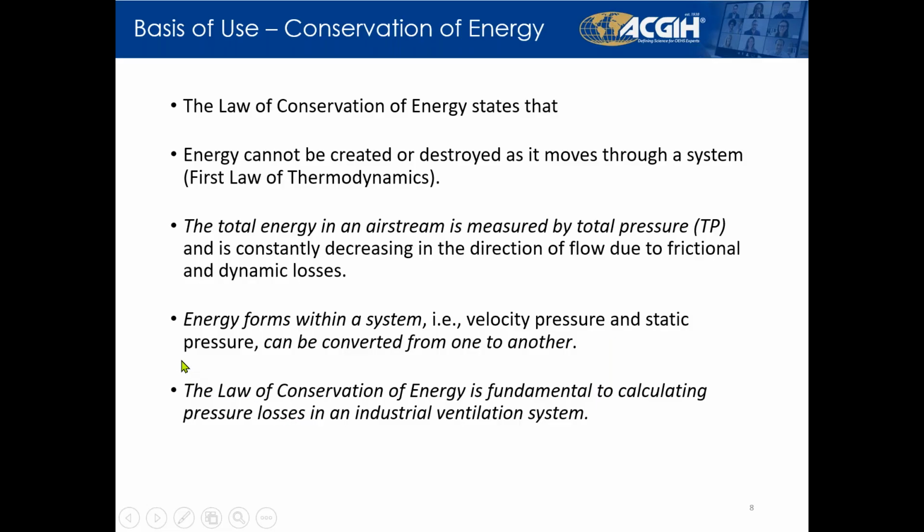Conservation of energy. The law of conservation of energy states, first, energy cannot be created or destroyed as it moves through a system. That's the first law of thermodynamics. Second, the total energy in an airstream is measured by its total pressure, and it's constantly decreasing in the direction of flow due to frictional and dynamic losses. Energy forms within a system, such as velocity and static pressure, can be converted from one to another. And the law of conservation of energy is fundamental to calculating pressure losses in an industrial ventilation system.